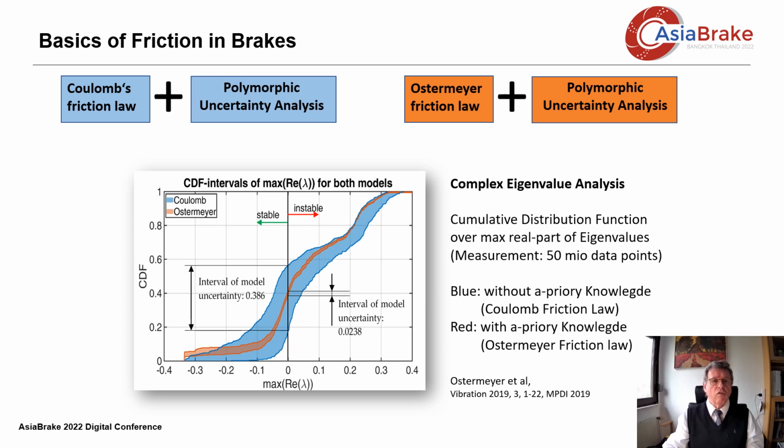The friction law can of course be improved, but already this first version of the friction law, which is more than 20 years old, allows much more detailed analysis in real-world NVH than Coulomb does. The key is the a priori knowledge on brake friction and its dynamics.